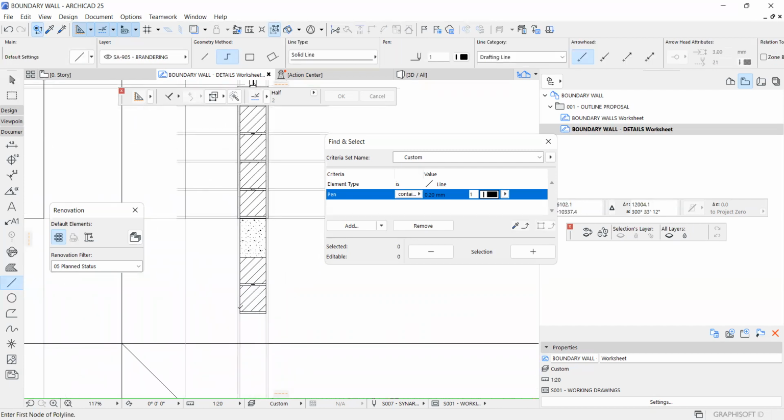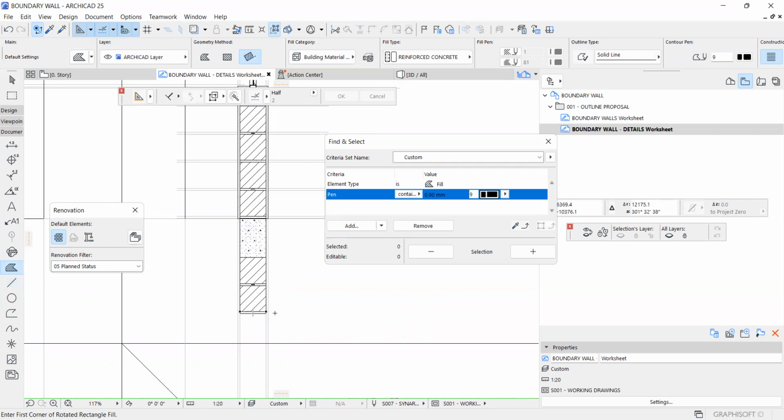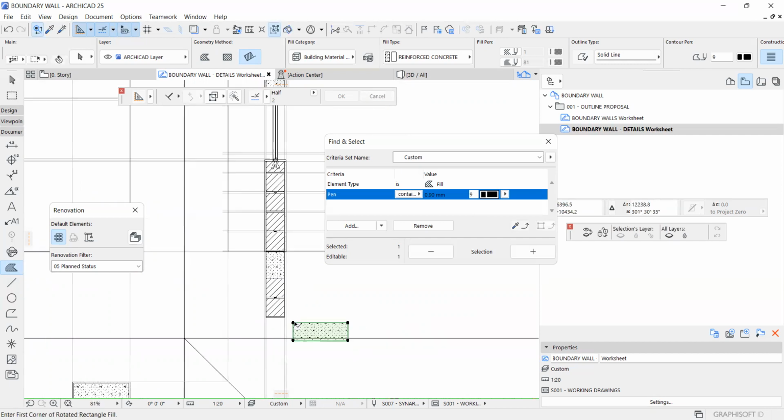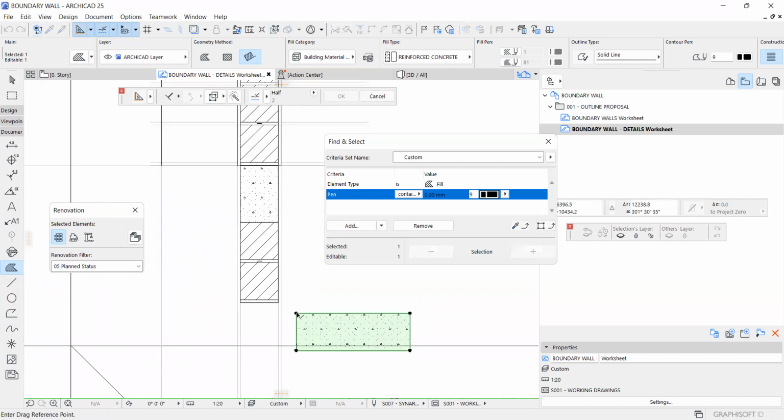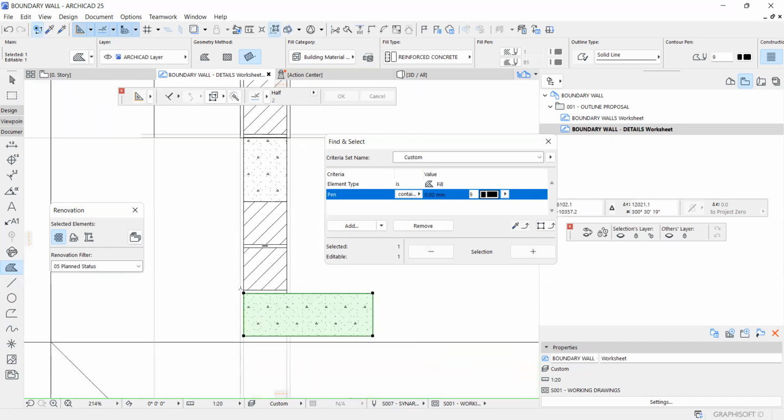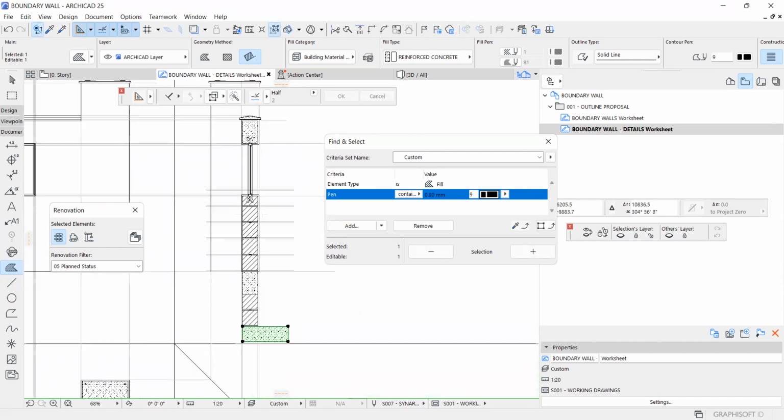And then below the masonry wall, we usually have what we call a strip foundation, a strip. Basically, I'm doing a strip foundation. So the strip is normally 600 by 200. But remember, it's on a boundary, so it will be what we consider to be eccentric. So you'll have something like that, okay? So that you respect, okay?